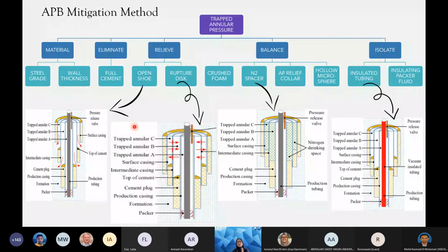But this one you have to cross check with your company's requirement. Like for us, we need to satisfy 150 meter cement coverage on top of the topmost hydrocarbon. And you also need to leave sufficient gap from your top of cement to your previous casing shoe. Why? Because if, over time, you have your barite settle, you thought you left an area for your pressure to escape, but you actually ended up plugging it. So you have to check these two conditions.